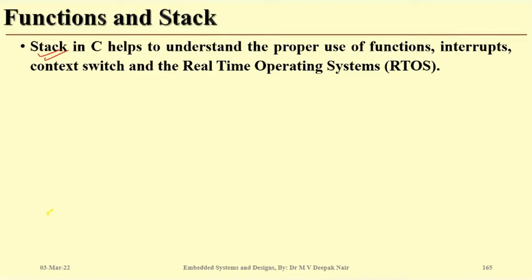Stacks are generally used to keep the data or the address of the next line from where a jump took place. Whenever we use a loop or branch instructions, the next address as well as some important data are stored in the stack.